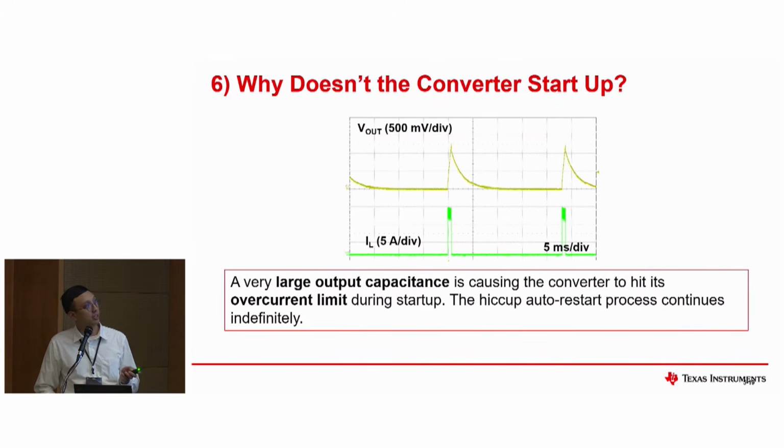As you can see here, as it starts up, the current shoots up, and then it triggers the device to shut down again. It keeps repeating because the device has a hiccup auto restart process. So it starts up and shuts down indefinitely.